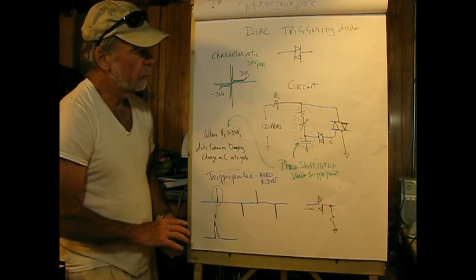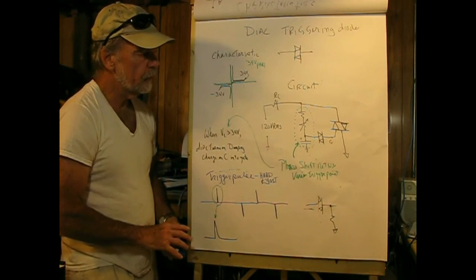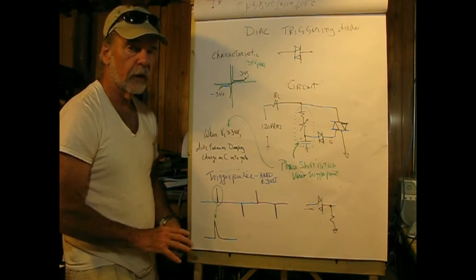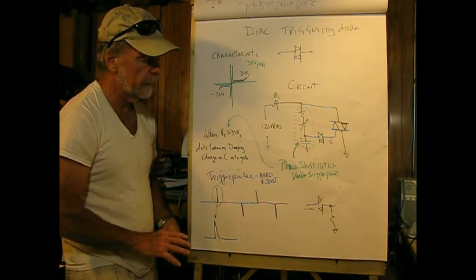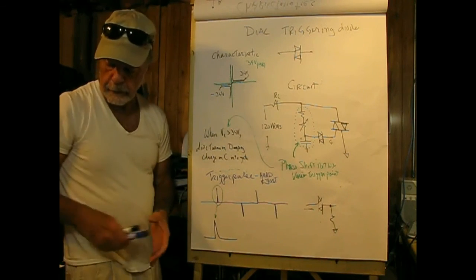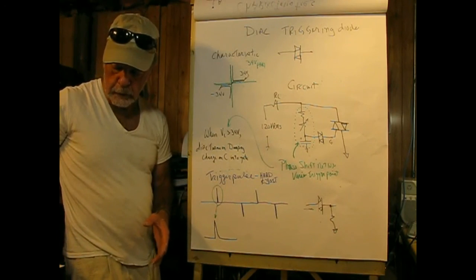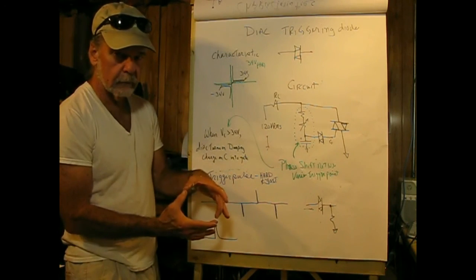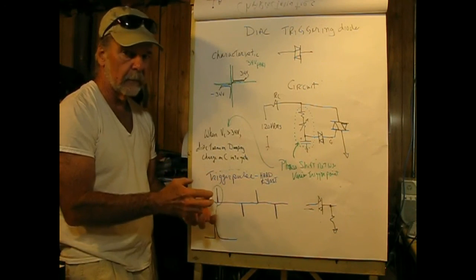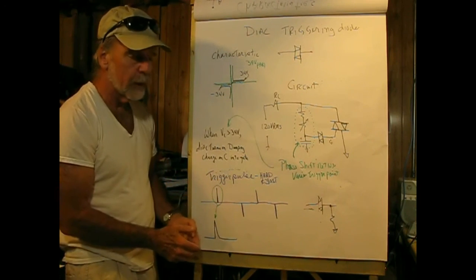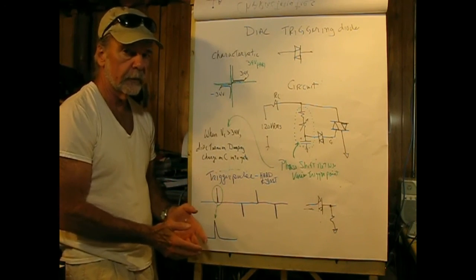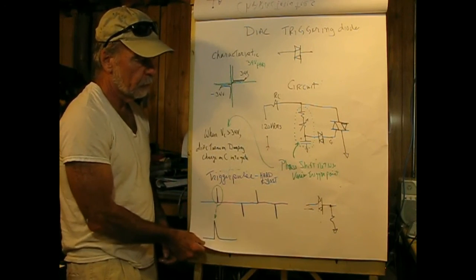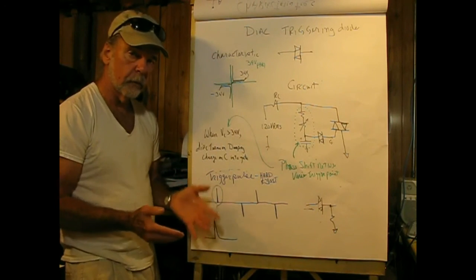So this is the workhorse for AC power applications, our SCRs and triacs, and some of them are like that big around with a great big nut on the bottom of them, so you can really tighten them to a large heatsink. So for AC control, these are the guys that do the work.